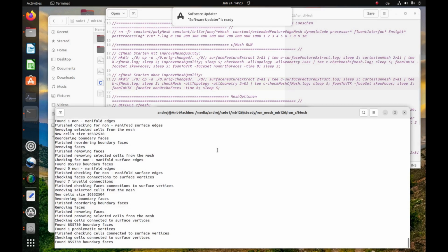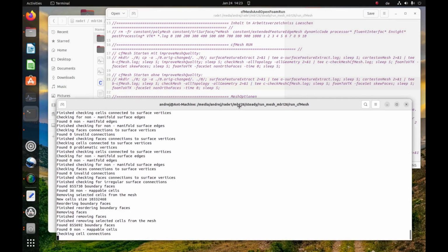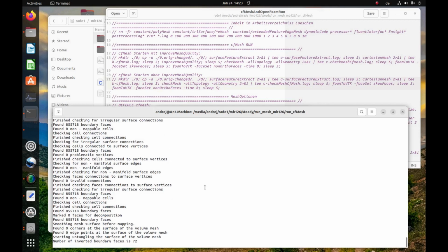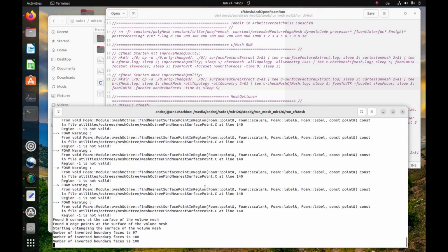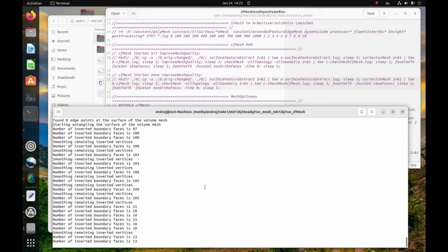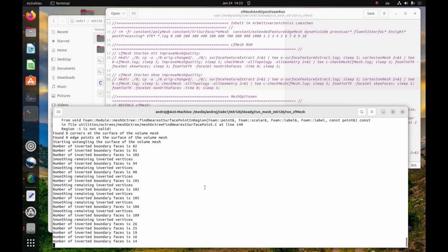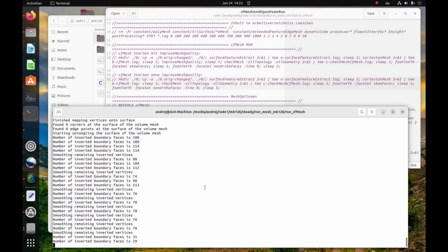It will be done automatically, but because of it sometimes we have problems with mesh quality. Let us run cfMeshDict and the cfMesh process, and after it is ready we will show the result and compare it with Snappy.